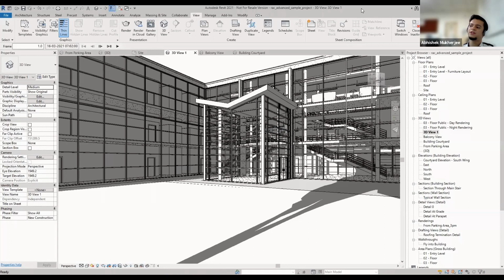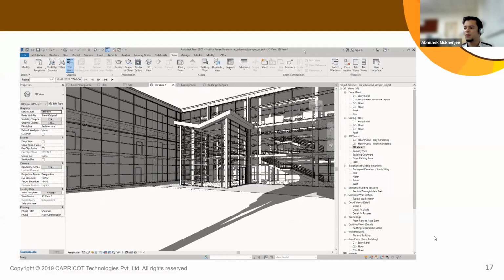And then after that, we can just go to any of the folders and view it as a video. So this is how we'll be able to do some of the initial decision making, and take decisions on whether we want a facade which is full of glass, whether it is shaded or not, and so many passive decisions which will be dependent on the shadow analysis. So this was a quick demo on the shadow analysis.